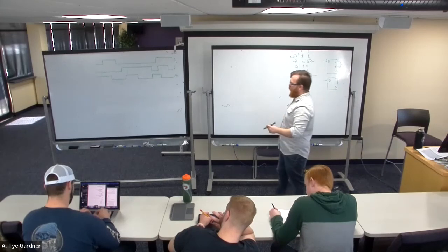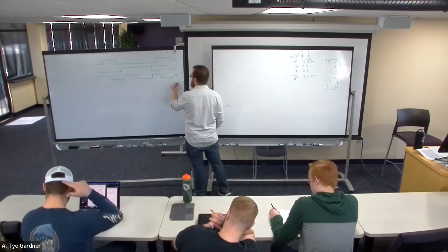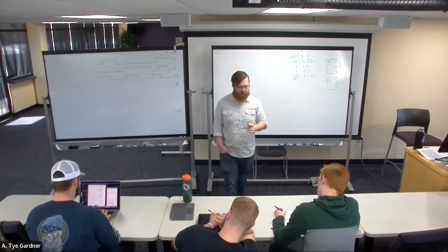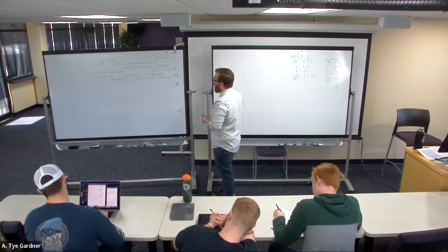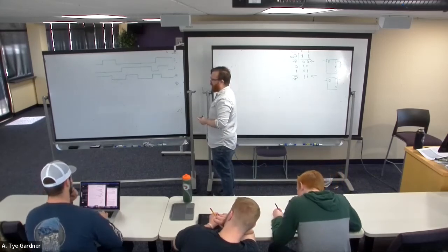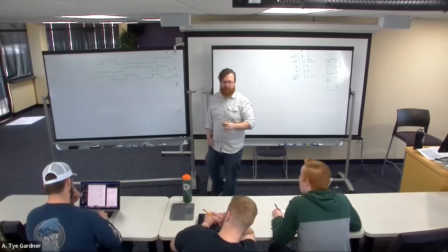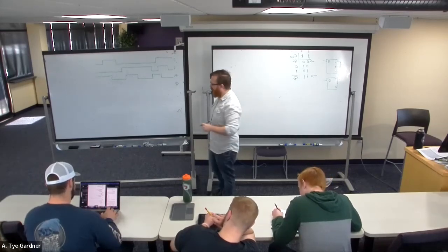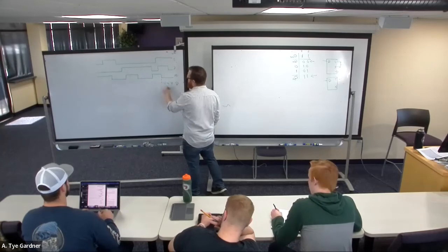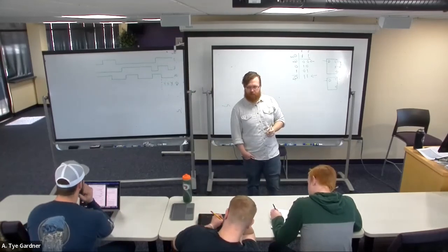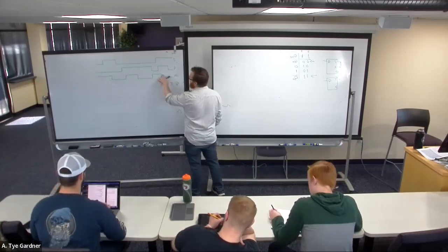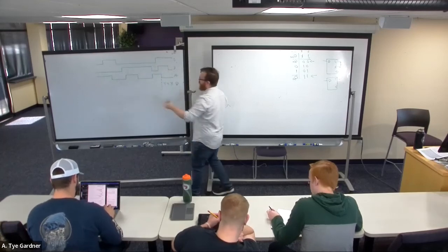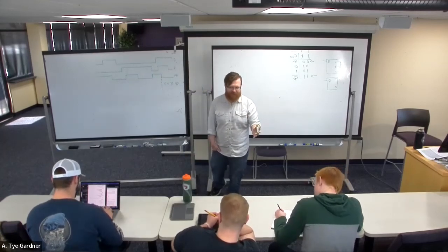So the nice thing is, once I know that it's a JK flip-flop, it's rising edge triggered, let's say, then I can just go ahead and say, well, what is Q doing? Well, in the beginning, J is 1, K is 0. But I don't have a rising edge of a clock. That's another way of saying, unless you have an assumption, until there's a rising edge, I don't know what it is. But once there's a rising edge, J is 1, K is 1. I invert. What's the inverse of I don't know? I don't know.